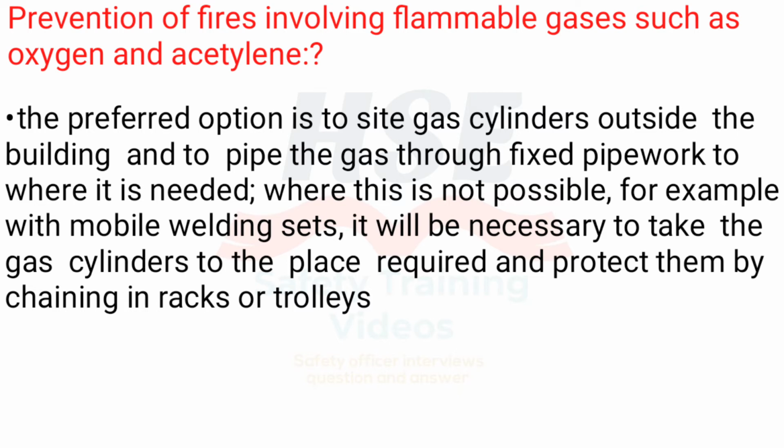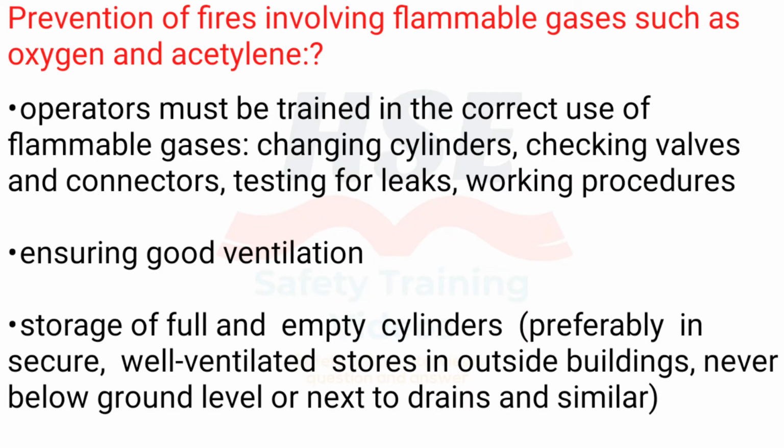The preferred option is to site gas cylinders outside the building and to pipe the gas through fixed pipework to where it is needed. Where this is not possible, for example with mobile welding sets, it will be necessary to take the gas cylinders to the place required and protect them by chaining in racks or trolleys.